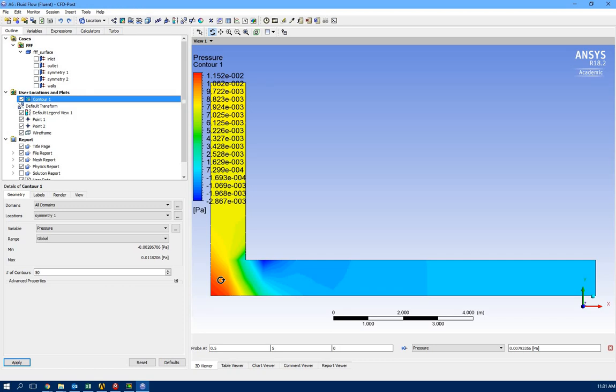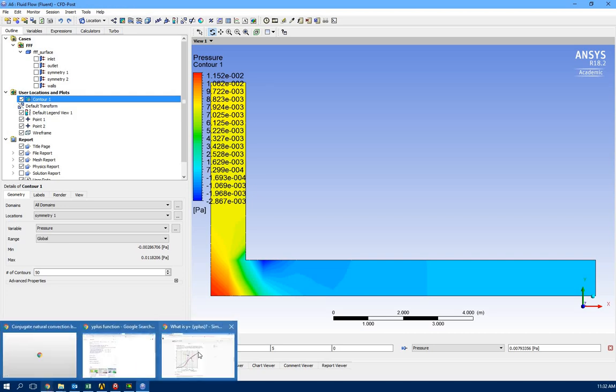We call it y plus, which is kind of showing how many mesh we have there inside that closed area, inside the boundary layer of the wall, which is usually, if it's a turbulent flow, going to be very thin. So that y plus is going to show us how accurate and how many mesh we have there to capture the behavior. Let me show you something here.